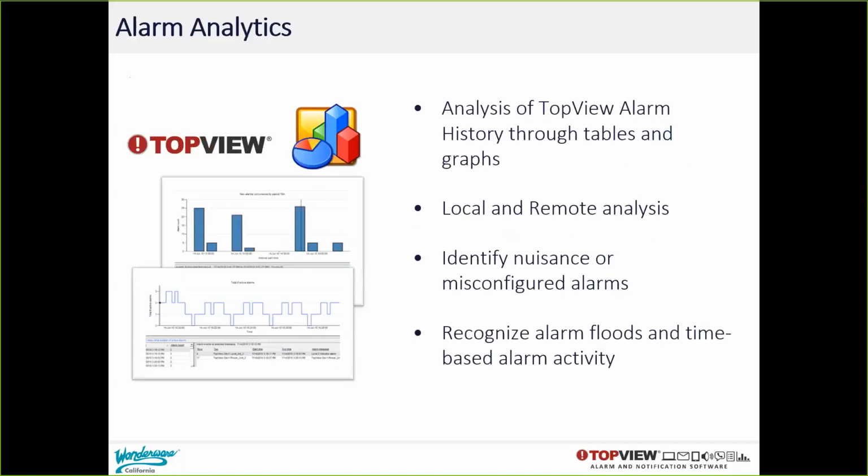Alarm Analytics is available in our desktop client and provides in-depth analysis of the alarm history through an interactive series of tables and graphs. With Alarm Analytics, we're not just showing you what happened. Instead, we're identifying the most frequent alarms, periods of alarm flooding, and periods with the largest number of overall active alarms. Alarm Analytics is an interactive exercise that allows the user to query, filter, and readjust the analysis in the hopes of identifying and reducing alarm activity.